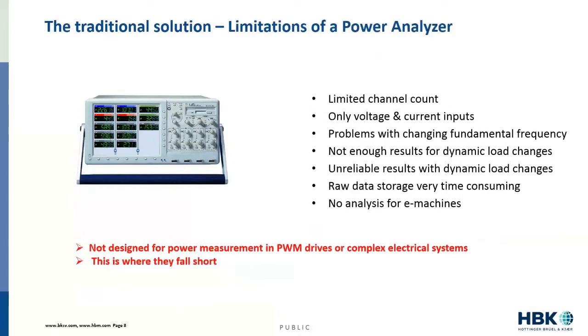Where you're going to get into limitations is when you start to try to use a power analyzer to do power measurements on PWM drives or complex electrical systems. In those cases, the 4 to 7 channels may not be enough. You may need other inputs besides voltage and current. Also, you're not guaranteed to have a static fundamental frequency that's the same for all the inputs. And in those cases, if your system is dynamically changing and you need to understand what's happening, you need to know that you're still getting accurate measurements and the system is sure of what's going on even during those dynamic